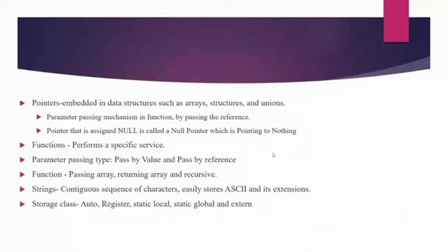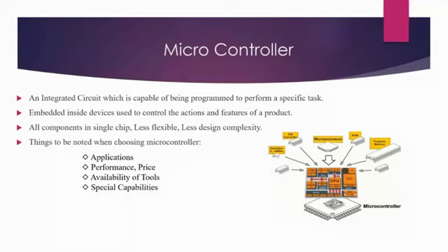Coming to the microcontroller, an integrated circuit which is capable of being programmed to perform a specific task. Embedded inside a device, it is used to control the actions and features of a product. Components are in a single chip, less flexible, less design complexity. Things that should be noted when choosing a microcontroller: applications, performance, price, availability of tools, special capabilities. This is the block diagram of a microcontroller. It has the microprocessor, A to D converter, RAM, program memory and oscillator.